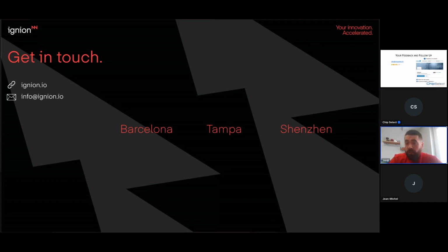Yeah, actually, this is a very good question. So we did a setup comparing a patch antenna, two separate setups, one for the patch antenna and one for the GNSS. It was a GNSS receptor built in our facilities, and then we performed the same examples for the four cases I explained before in the car: the rear front, upper seat, and below the seat. And then the TTFF was quicker. We have a quicker acquisition for the Ignion antennas.